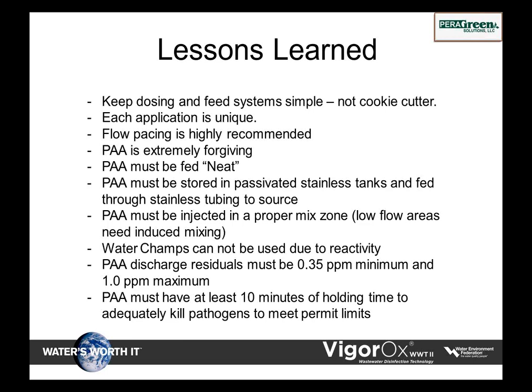And also, you know, we would like 10 minutes. I've seen places now where I have to do 5 to 7 minutes. You can achieve it. It's a CT variable. You're going to have to go with higher dosages. But again, you still have to achieve less than 1 part max in the discharge.